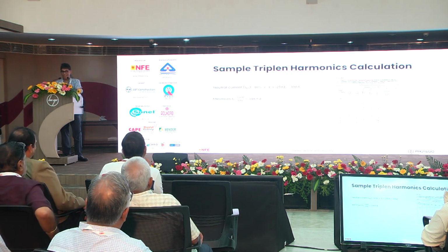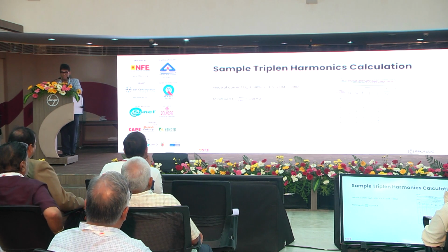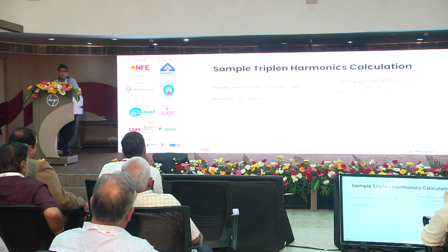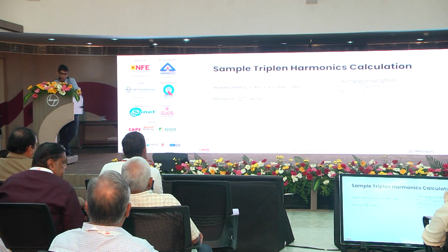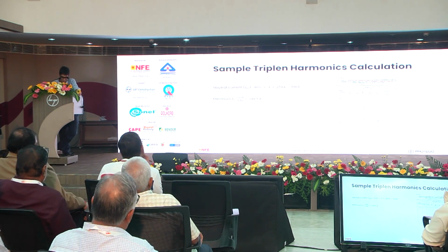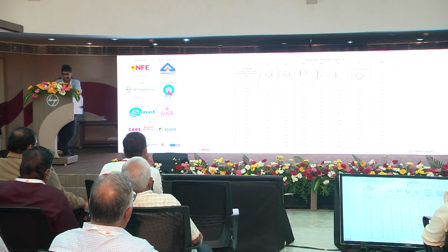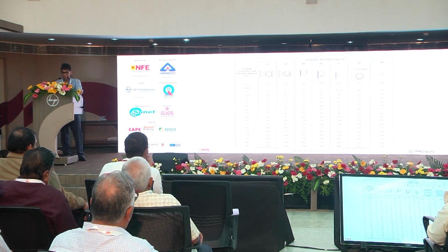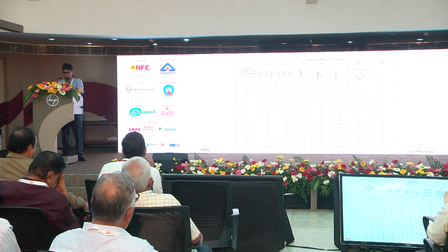So, now you all forgot about something. What happened to the derating factor? 300 amps is the current, correct? But how many loaded conductors do we have? We have 4. So, we need to do a further derating. So, actually, we need a 240 square millimeter cable, because the 0.86 factor kicks in.